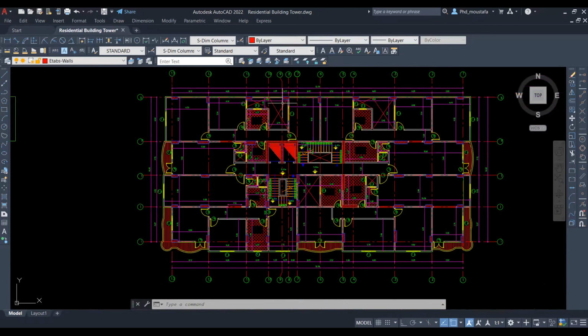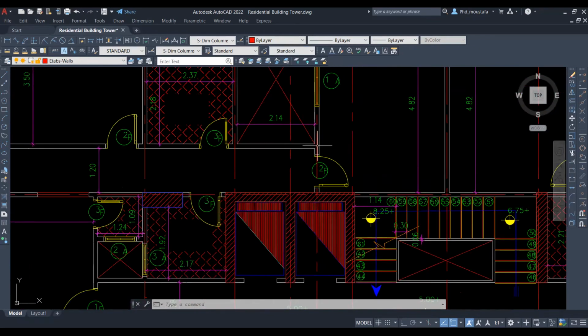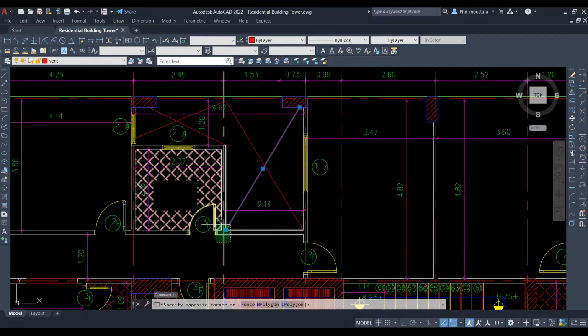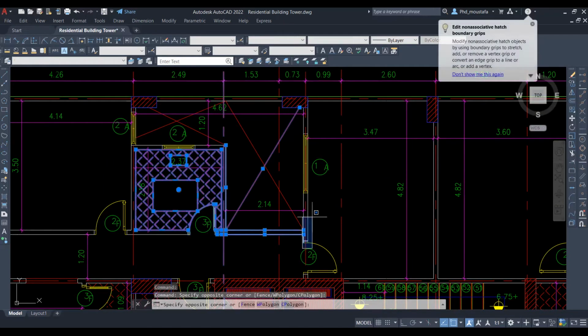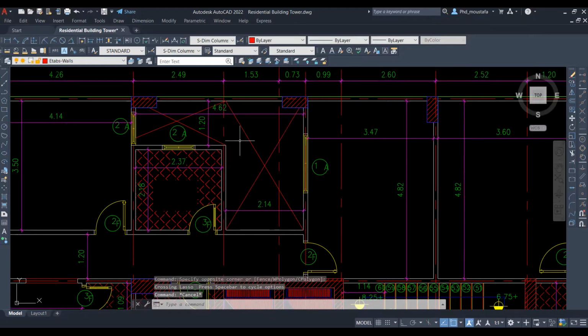So please take into consideration the voids, because around the voids they have a specific design. Usually we put 2 rebars here up and down, 2 rebars here up and down, because usually in the corners, in these edges, cracks could happen. So we always reinforce the edge of the opening.